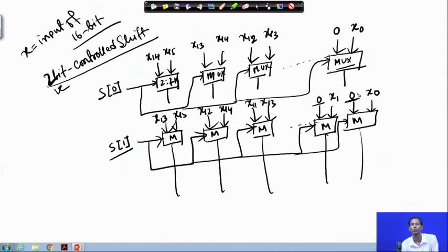the LSB position. The same thing if I need 4 bit control shift operation. At that time 4 zeros will be added. For 8 bit operation, 8 LSB positions will be padded with 0. So, this is for 1 bit, 2 bit, 4 bit and 8 bit.